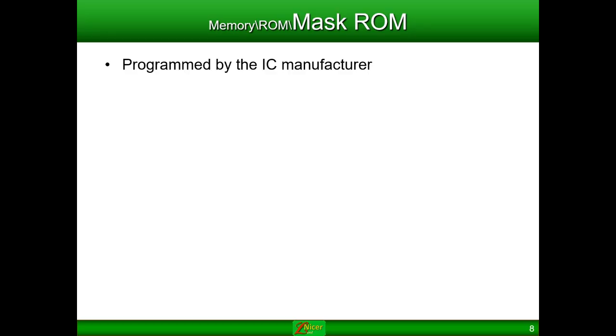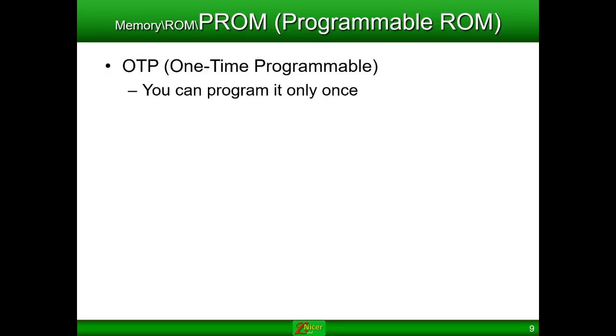Programmed by the IC manufacturer. As I told you before, this type cannot be erased by a user. The code is burned into it, and a normal person cannot change it. Then we have PROM, one-time programmable. You can program it only once.